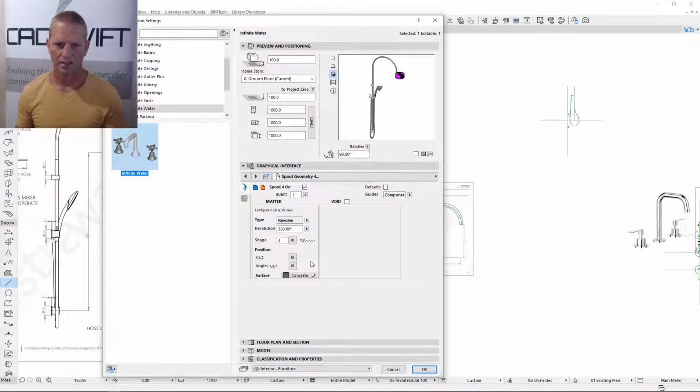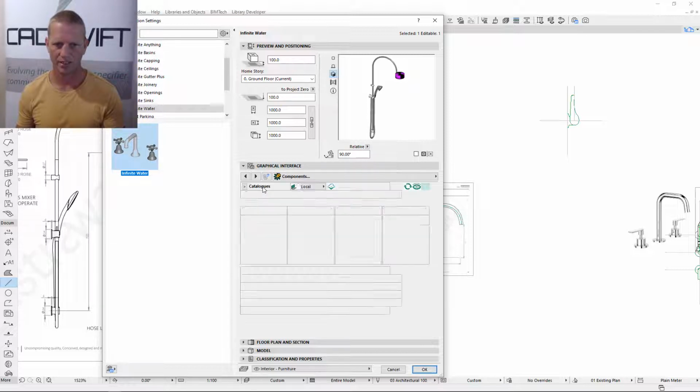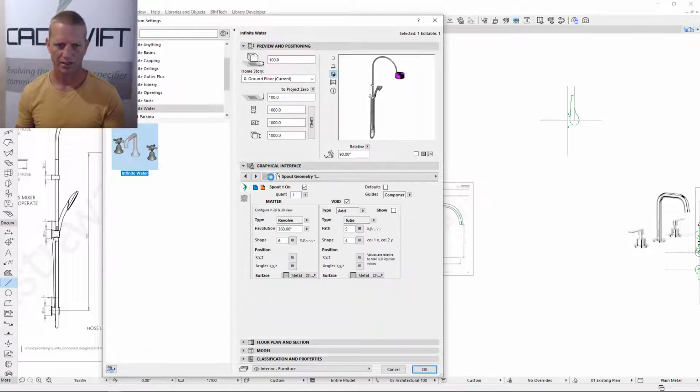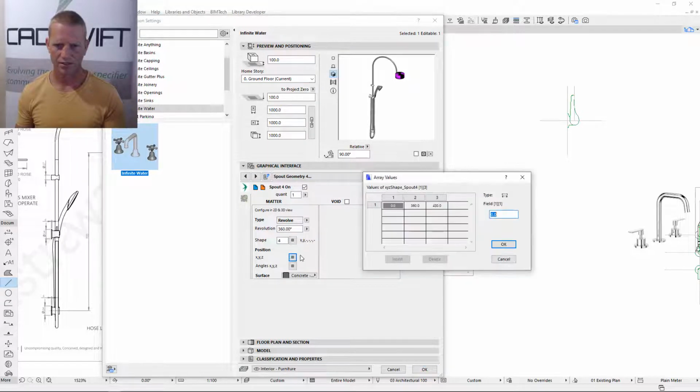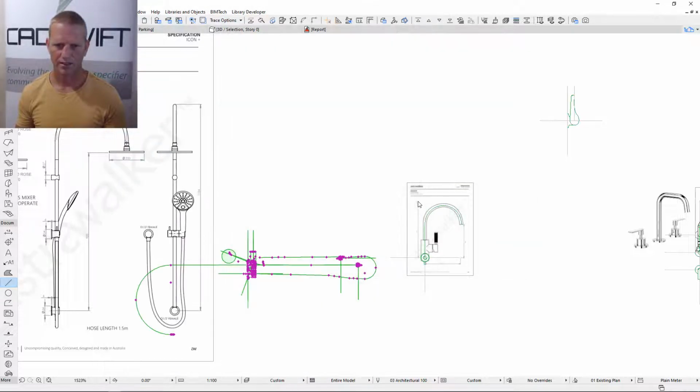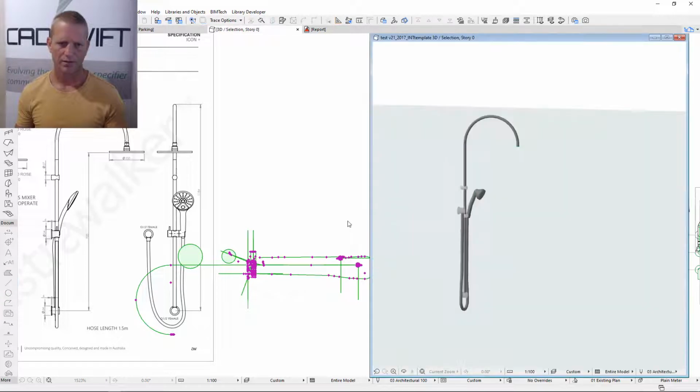Okay, and it doesn't look like we've got our positioning right. Oh, because we've already got the positioning of the other element. So the spout, if we have a look back here, the spout is positioned at -30, and we wanted to go out to -430. So we go back to spout, back to our geometry 4. So the position should just be 400. Click OK. Have a look.